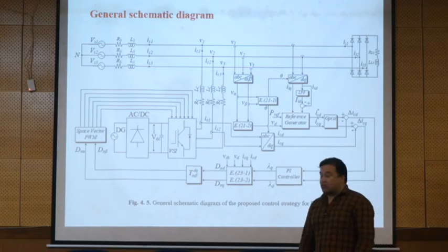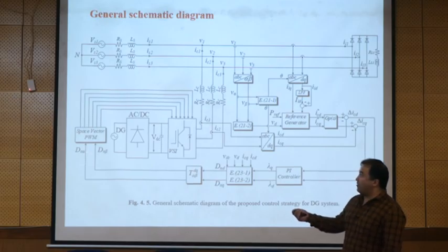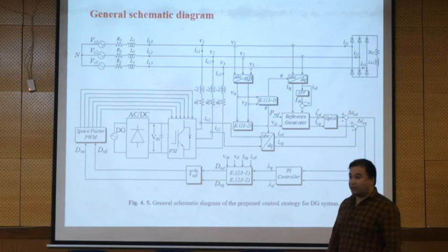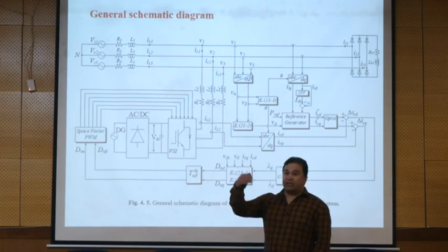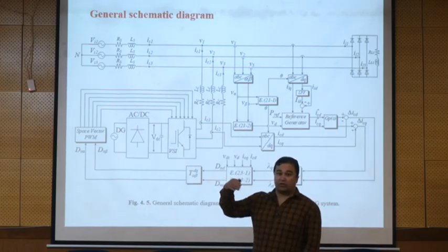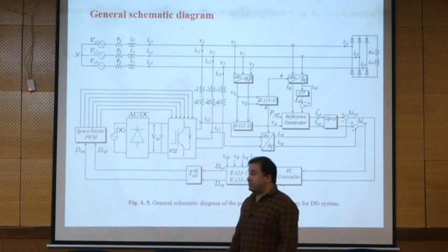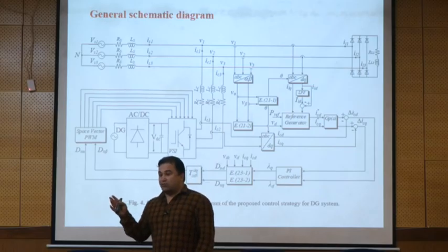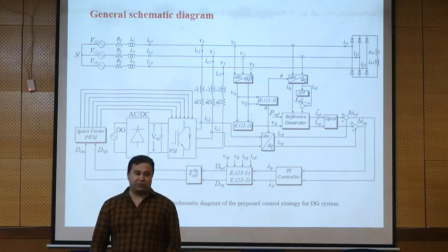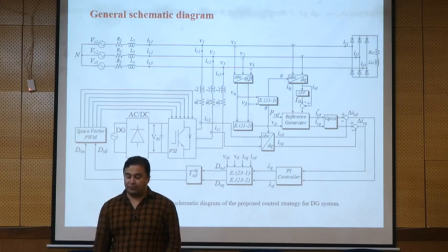Okay? So then we use the dq to alpha beta transformation to change it to D alpha and D beta. The reason for this is that when you use the space vector PWM, the input duty cycle, or switching state mode, should be in alpha beta and not dq. And the reason is that when we go to a space vector, I don't know, should I explain to you why, or do you accept it as it is? Explain it? Okay.